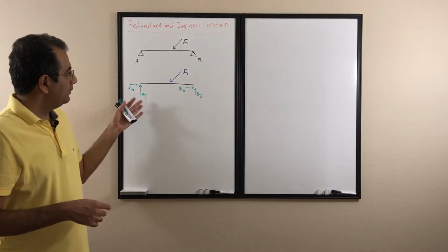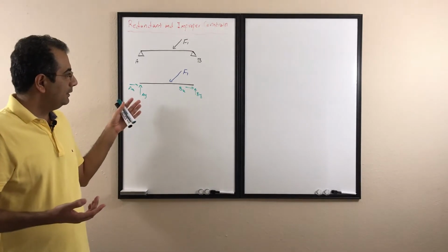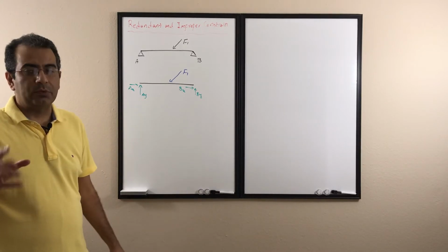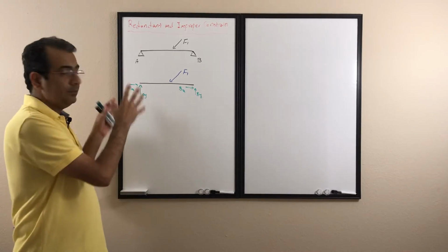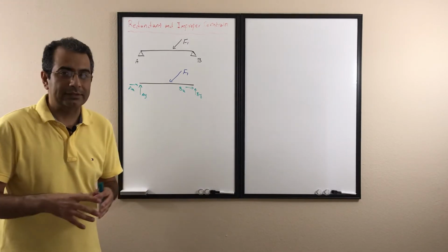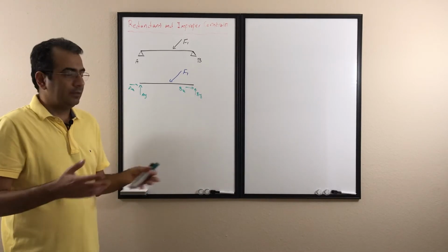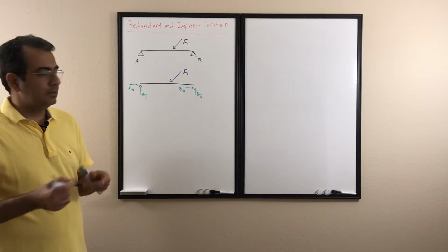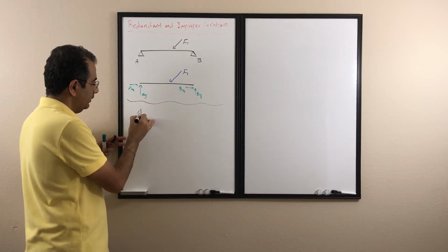So when we have cases like that, we have a redundant support, or in other words, it is indeterminate. From the statics point of view, we cannot determine AX, AY, BX, and BY with what we know from statics. Later on in other courses we'll learn how to do that, but here in statics, based on what we know, we cannot solve this problem. So it's going to be indeterminate for us, we cannot solve it. That's how we call it the redundant support or constraint.